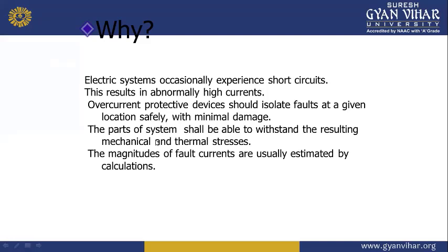Depending on the arcing or arc interruption time of the circuit breakers, a suitable reactance value is used for the circuit model of the synchronous generator for short circuit analysis.